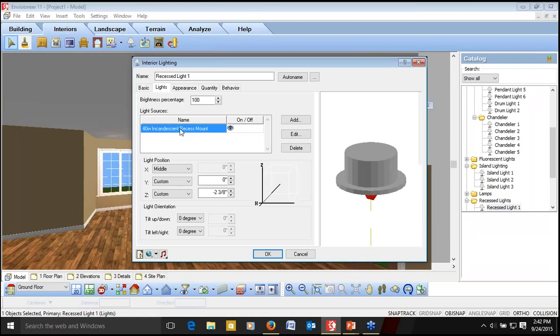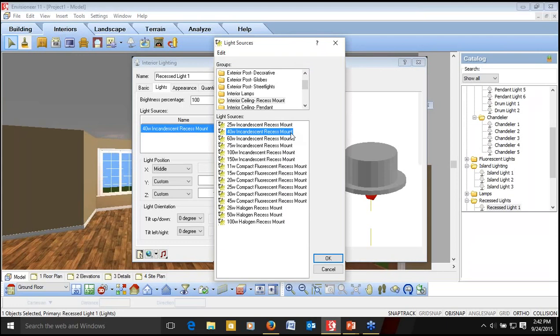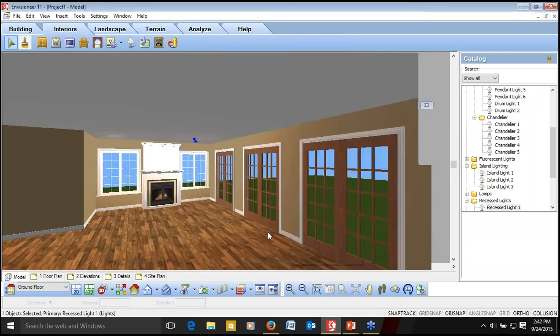And you can change and edit that to any wattage, so you can directly show your clients the effects that lighting is going to have on their overall design as well. So if they want to maybe leave out a couple lights that you think are vital to the design, you can show them just how dark it's going to look throughout the entire model except for that one space. So it really helps to illustrate those issues.